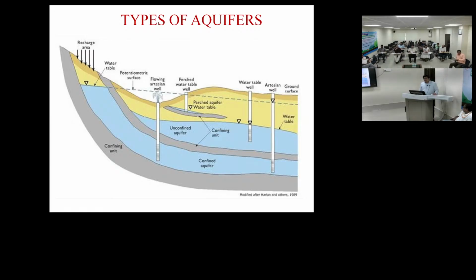This is a very good layer, good in the sense of gravel and sand. We thought we would get a very good potential amount of water. But the water was very meager. Due to urbanization, everyone has tapped those aquifers, and after tapping, it is completely desaturated. Practically, by finding those layers we should get a good amount of water, it should be a good aquifer, but because of desaturation and continuous pumping, it is desaturated. Those situations have to be taken into consideration.